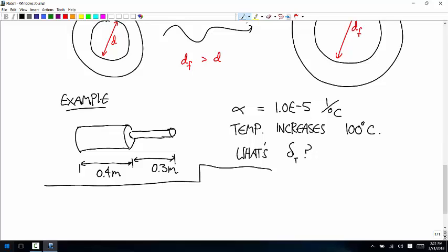So if you're talking about a temperature change of, I guess, 500 Celsius or something, a little over that, 500 Celsius times 1 times 10 to the minus 6 times whatever length dimension it is, you get a pretty big percentage change in the sizes of things. And when you think of it that way, it makes sense that your car drives so weirdly before the engine warms up.